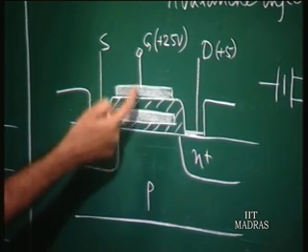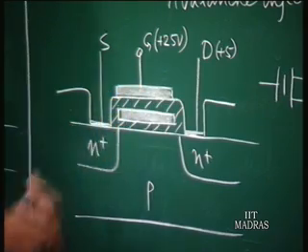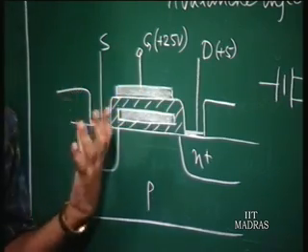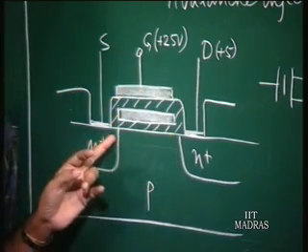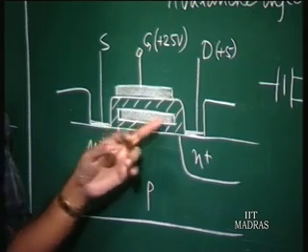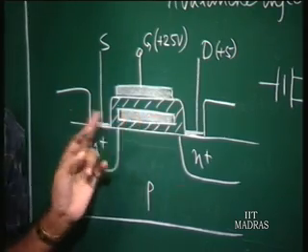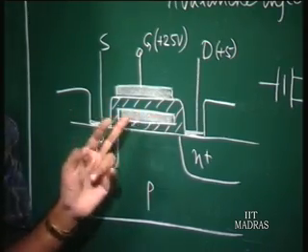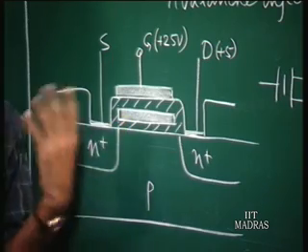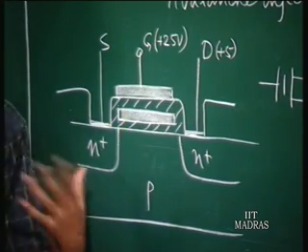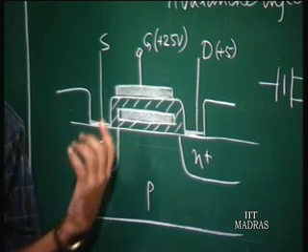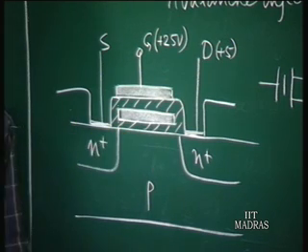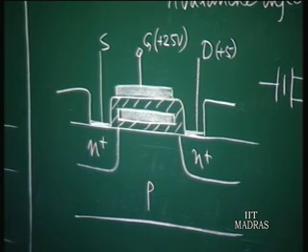So, you have a floating gate and the control gate. You must apply a much larger voltage at the control gate to create the channel, in order to overcome the effect of the negative charges on the floating gate. So, basically the threshold voltage is increased by this process of implanting negative charges on the floating gate.